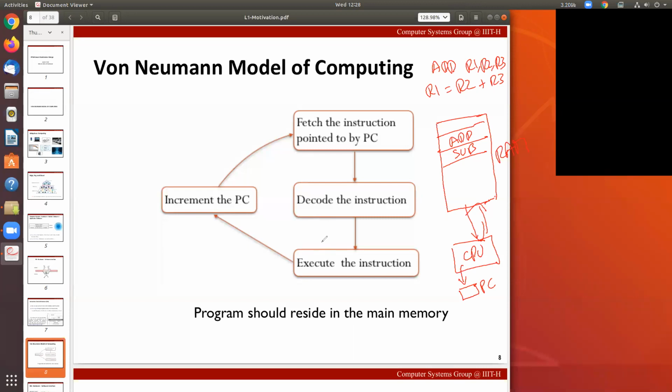It usually increments the program counter, but if it hits a branch instruction, which could be an unconditional or a conditional branch, then depending upon the outcome of the condition and the branch target address, instead of fetching the next instruction, the processor will fetch the instruction present at the branch target address.